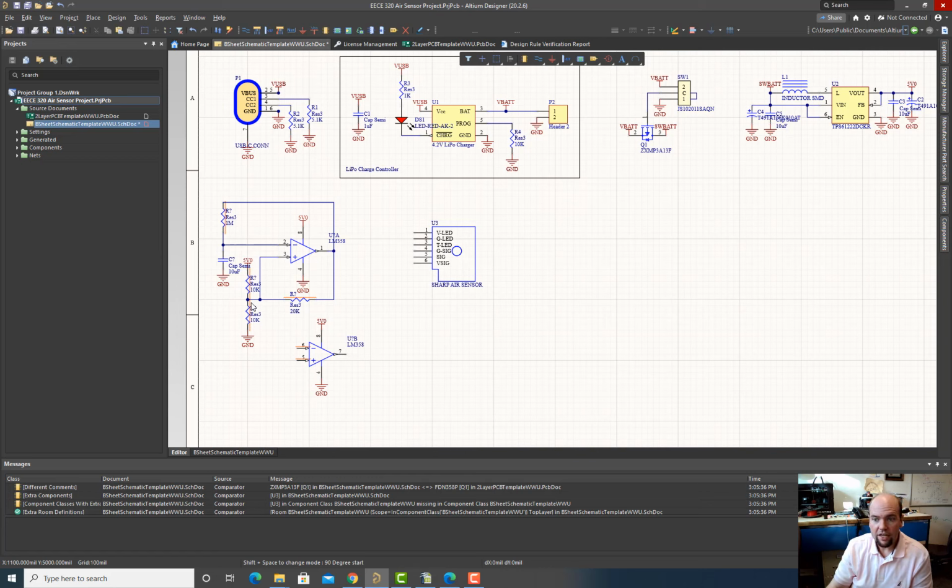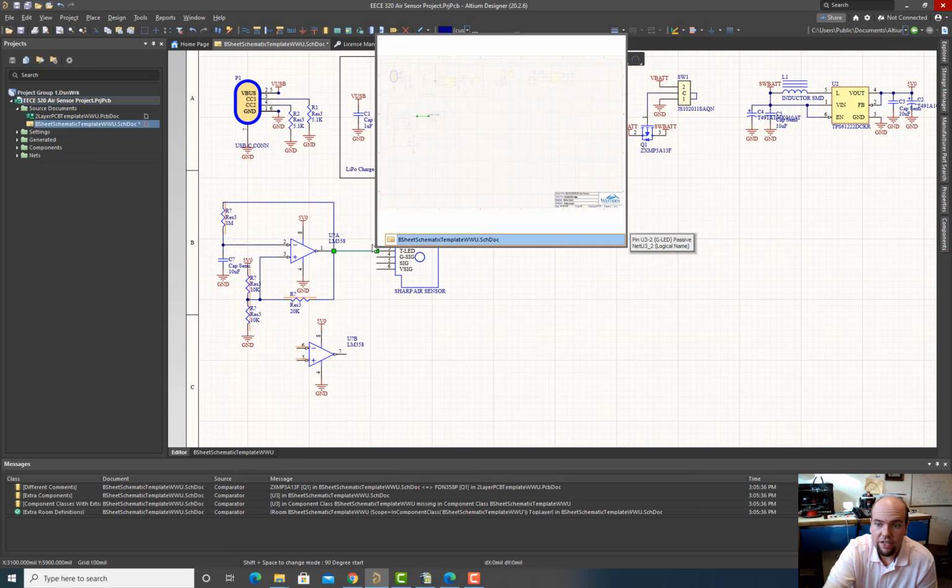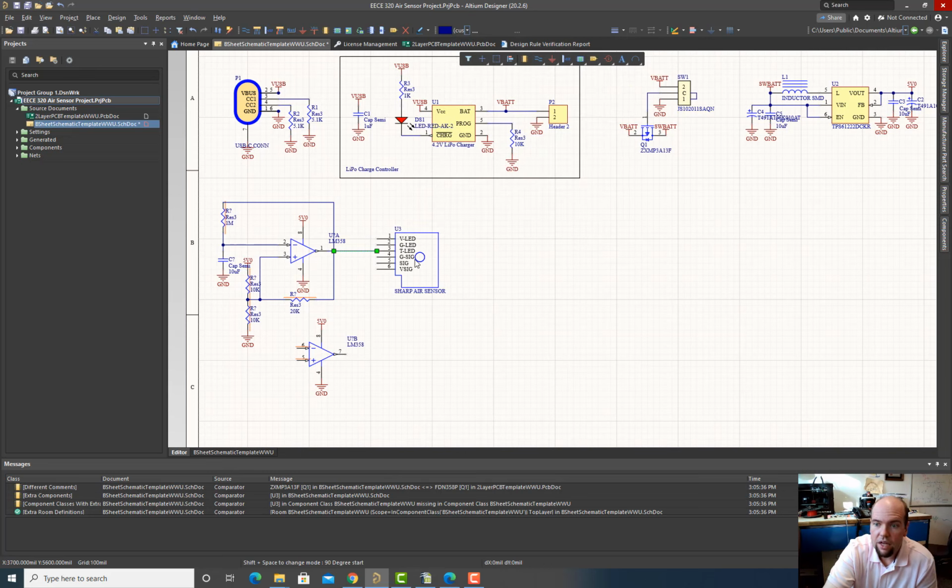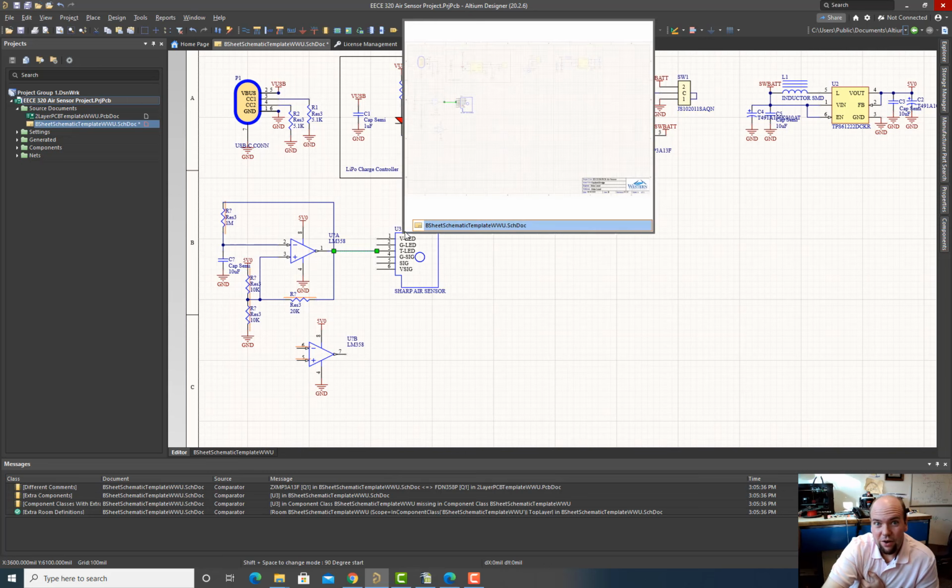But for us, this is generating this pulse train. And this pulse train has to be connected to the T LED. This is the trigger LED signal. So this pulse train has to be connected to the trigger LED. Now the ground LED, that's just going to be our system ground. And the V LED, that's going to be our 5-volt signal, but it's got to go through that filter.